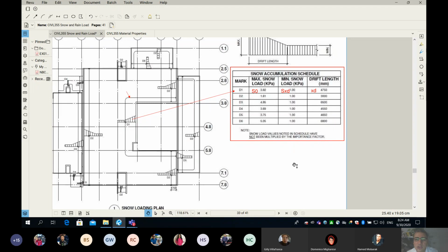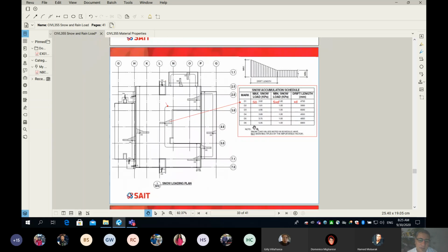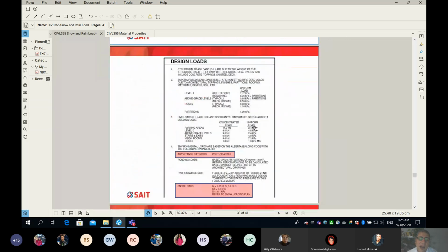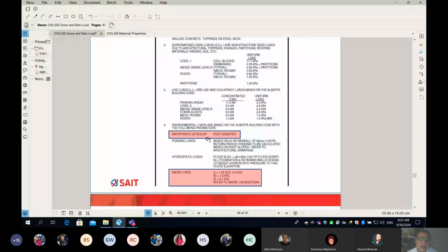But when he or she wants to change the drawing, they don't have to touch the plan view. The plan view will stay the same. However, they have to change the number in the schedule. This is, again, a fantastic invention. We will keep talking about schedules in columns and beams, because otherwise there would be a lot of errors if you don't use a schedule. Okay, now, final comments on this part.